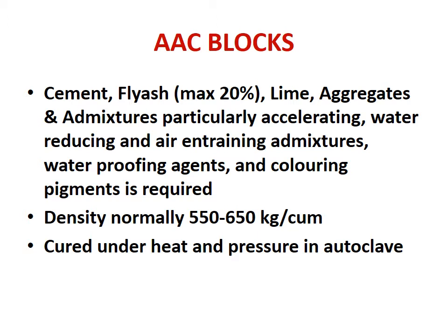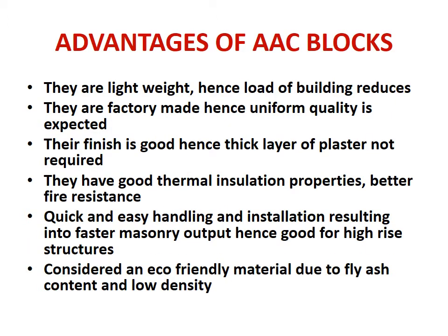Density normally what we get in the market varies between 550 to 650 kg per cubic meter, and as we know the density of water is about 1000 kg per cubic meter, therefore they are quite lightweight material, and they are cured under heat and pressure in an autoclave. That's why the name AAC.